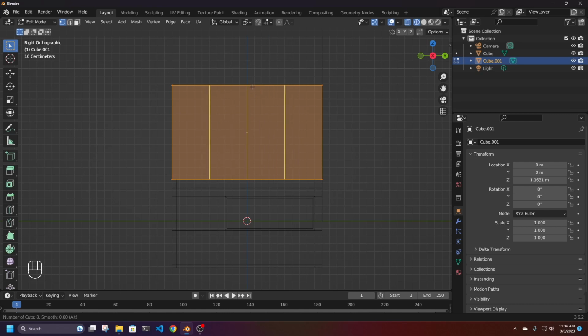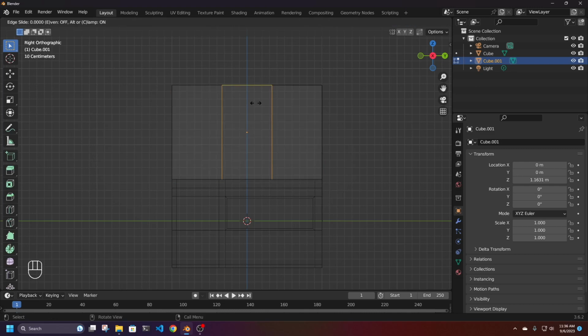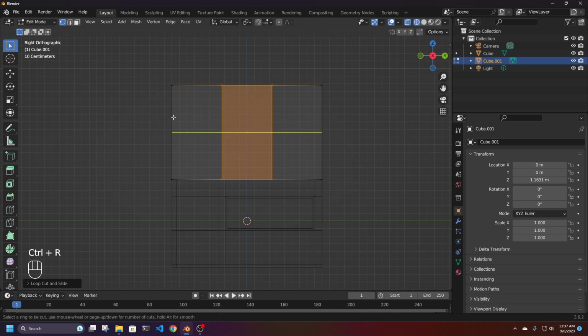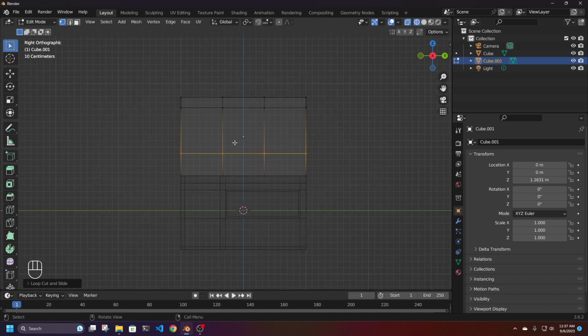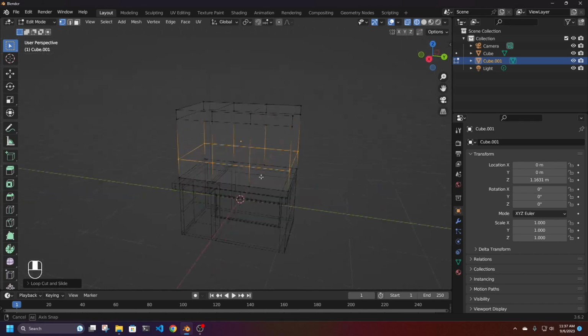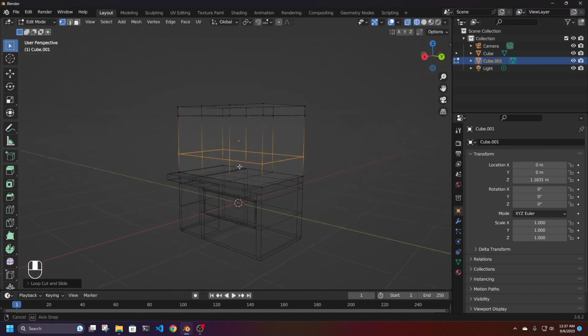If you see two yellow lines, that is fine. And then you click first, and then you right click to release it. Now press Command R again and go to this edge, click and move it up a little to somewhere here. Command R again, click and move it here, and that is fine. Great. Then use your middle mouse to create this angle.